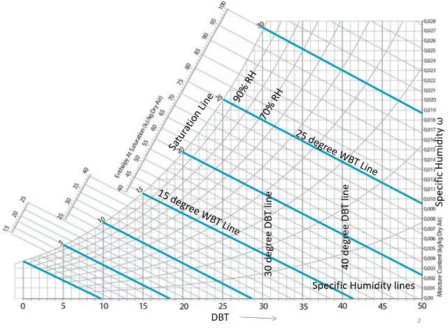Now suppose you want something in between, for example 13. Then you have to count 11, 12, 13 from 10, where it touches the saturation line. From there you have to draw a line parallel to this blue line. That indicates the constant WBT line of 13 degree. So anything, for example, if you want 24, 23, you have to draw that line.